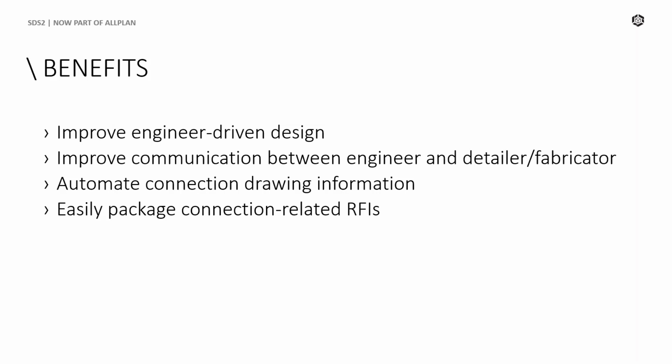2 or 3 connections, it could encompass anything perpendicular coming in, skewed, whatnot, and check those for buildability in the shop, erectability and constructability on site, scaling these connections so that everything is very visible about how it can be built. If it can be built, is there anything clashing?